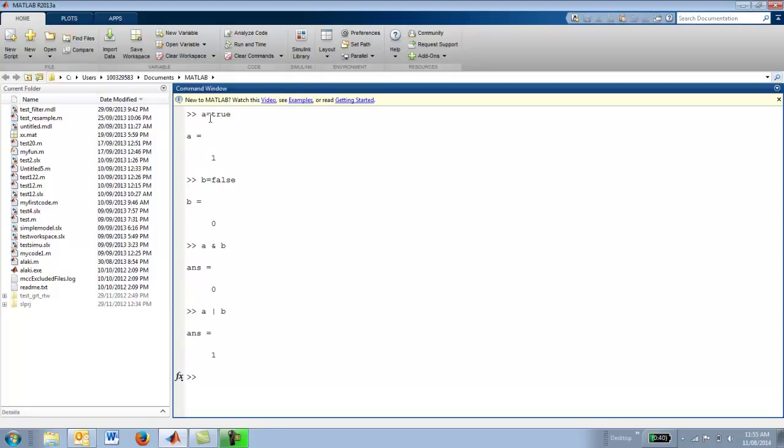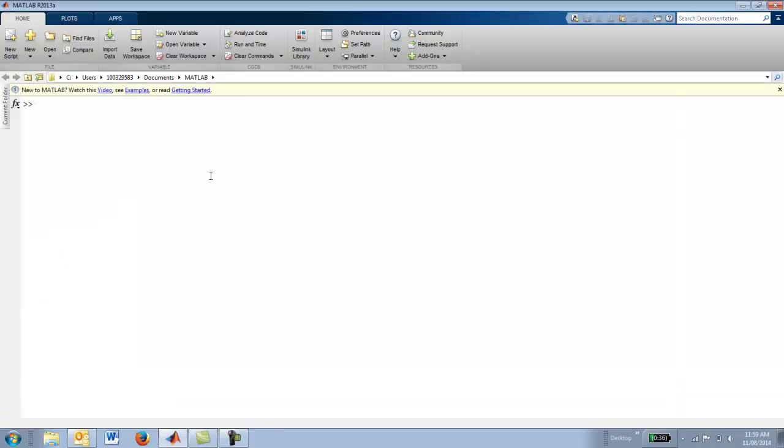Okay, let's see how in Matlab we can compare the parameters together and take an action based on the comparison. So let's define c equal 2 and d equal to 5, and I'm going to say if c is less than d, then assign 1 to variable w, and then I'm going to end the comparison. So in this way, because c was really less than d, then w was assigned 1. So getting this echo back from Matlab means that this comparison was done.